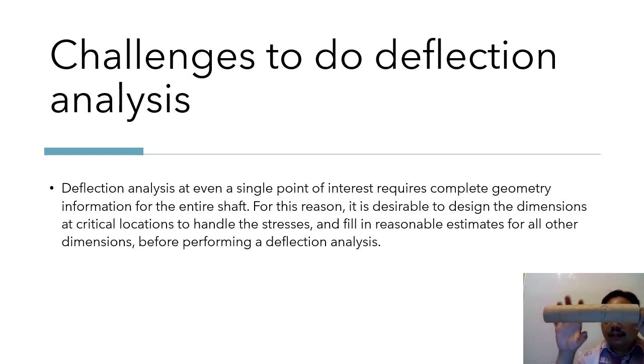The simplest idea is you first calculate at the points of contact with the gear, shaft and pulley. Let's say this clamping point is the point of contact with the shaft, bearing, pulley and flywheel and everything. You calculate this first, and then you calculate the shaft diameter and everything at all other points. This is also challenging, and it is suggested that if you have software, it is better to do it with help from software. For initial analysis, you can do the calculation by hand.